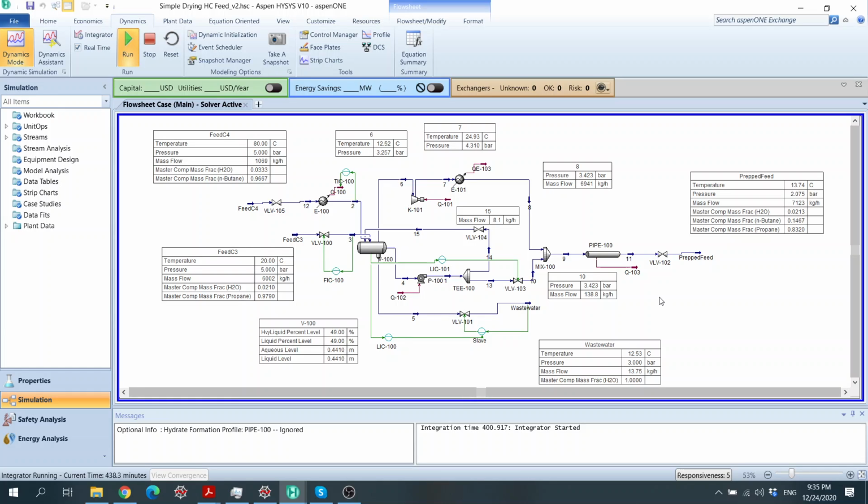And now we can see it's running smoothly. By this point, I think you understand what it takes to do a dynamic simulation. Just to recap, in dynamic simulation it's better to use the pressure flow solver, so the flow is defined by the pressure balance.